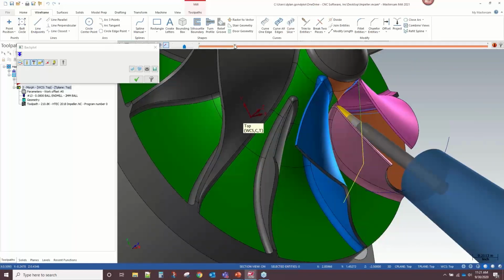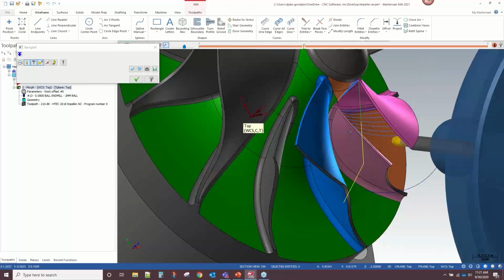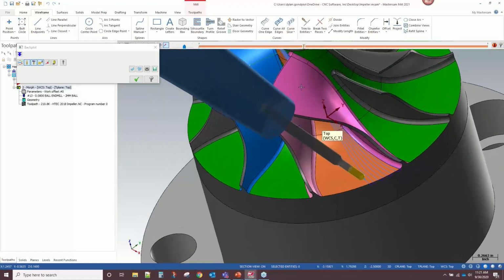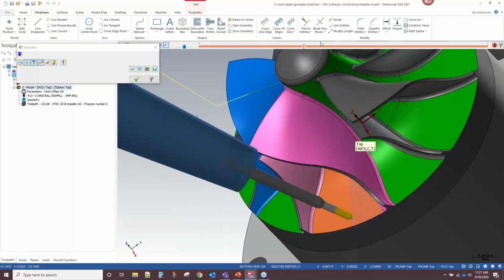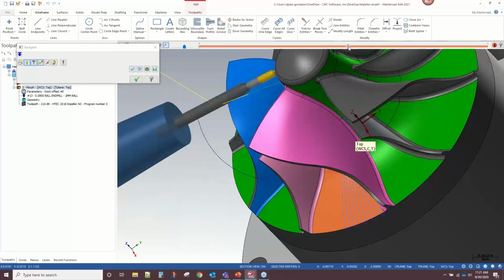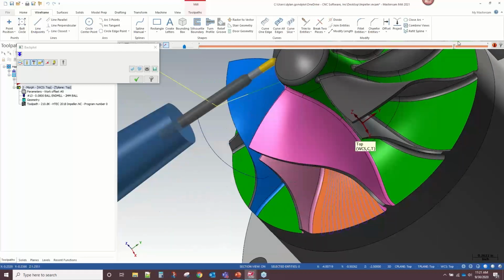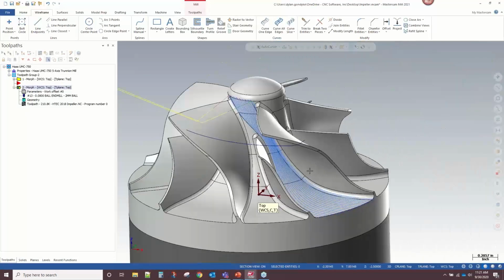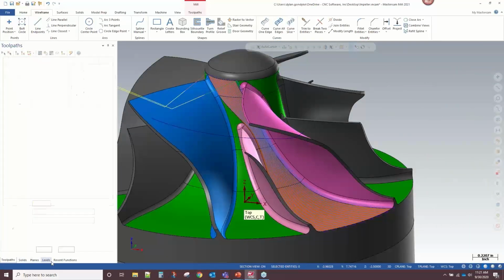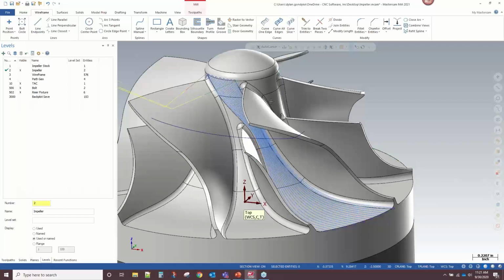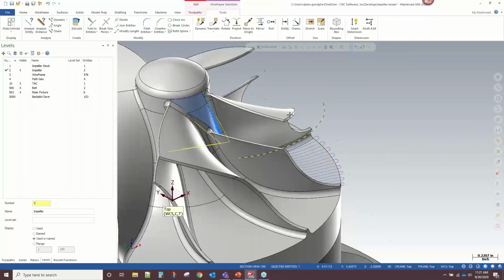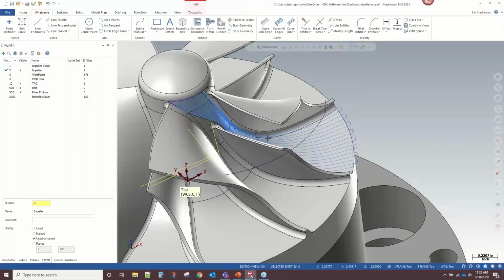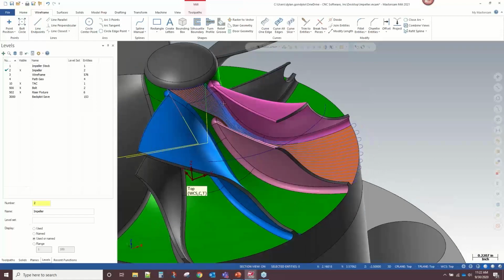So for every single pass on this part, we've taken that good motion that we found in the last pass, and we forced it explicitly for everything in this toolpath. So we've just programmed this really complex throat area using a simple wireframe spline that took us about 3 minutes to generate from scratch, and it's totally approximate.